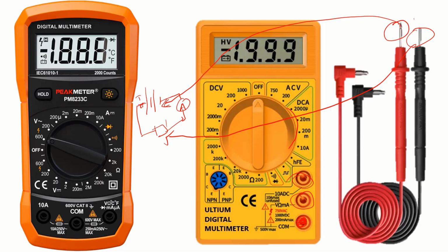You might also be given crocodile clips in order for you to fasten your wires together to ensure good electrical conductivity. They are always given. Now when current is passed and your multimeter is connected as shown in the circuit, if the reading on the screen is 1, it means that the current flowing through the resistor does not belong to the range where your multimeter is set.